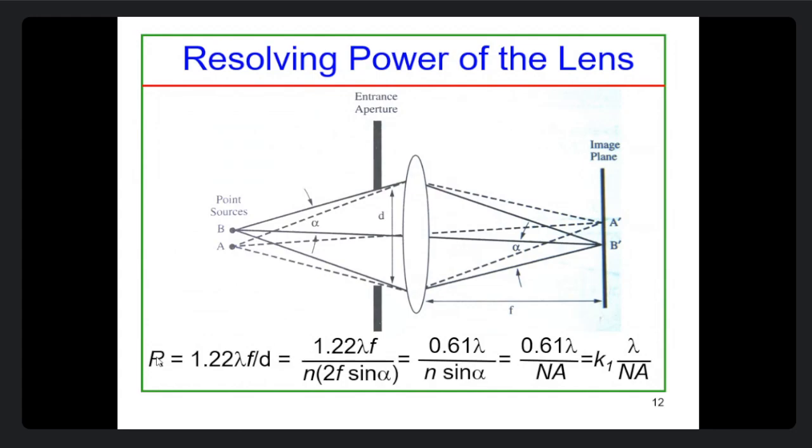Or you can say the w mean, the minimum dimension or minimum image line or feature size, whatever word you can use, that will be reduced. So mainly in this way, people also view the k value. Anyway, this expression is called, that is R or w mean equals finally k lambda or k1 lambda by NA. This is called the Rayleigh criteria. Okay, Rayleigh criteria.